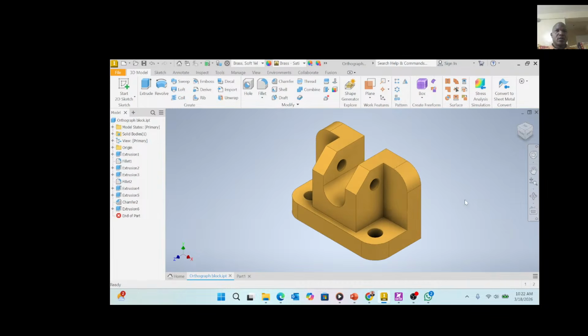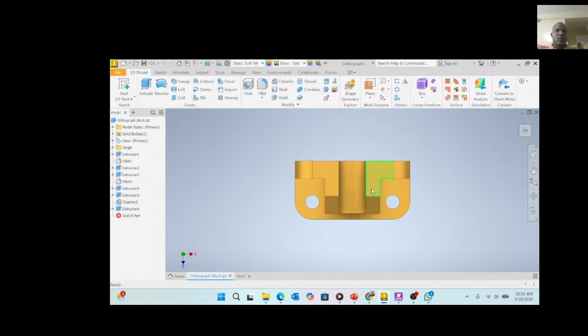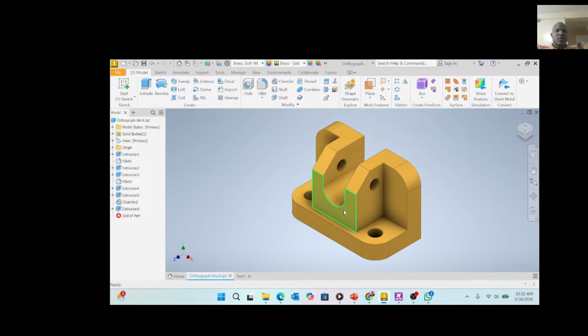I will take you back again. But also hidden features can be illustrated differently. For example, if you are from the plan, pay attention. This is a hole from here. In this top view, you can see these horizontal holes through it. But if I select, still you can see it. You can only see these holes that are in direct perspective to your eyesight. Now, let me go back to the home view and have an understanding of what we call the cutout that was in these.